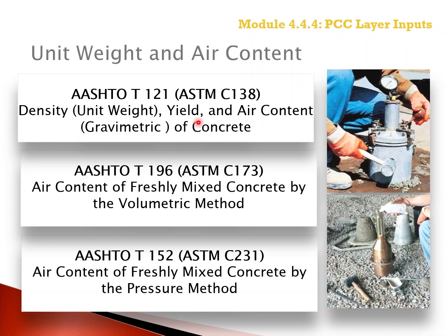The photo in the upper right shows a pressure meter air test. This is the most commonly used device, but is not appropriate for lightweight or porous aggregates. The photo on the bottom right shows a volumetric air test that can be used for all types of aggregates.